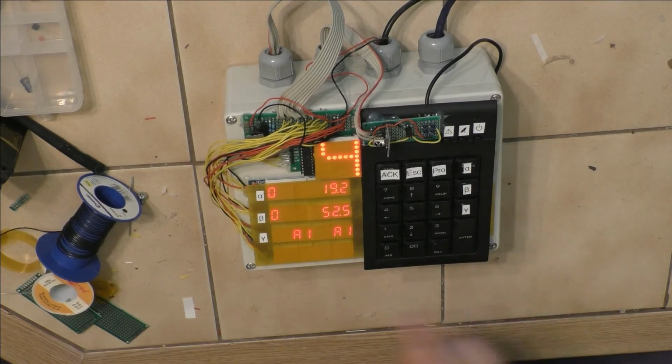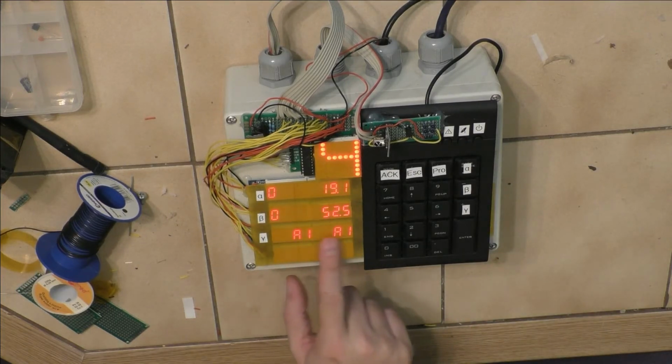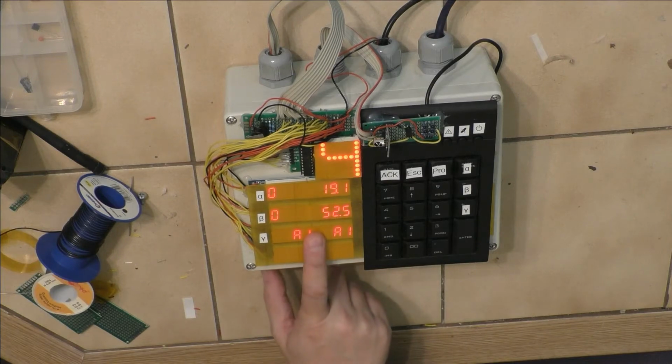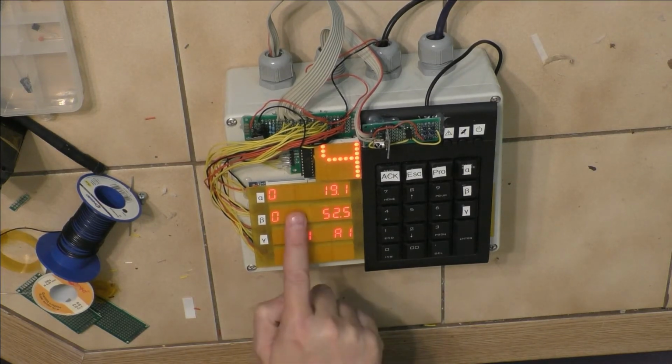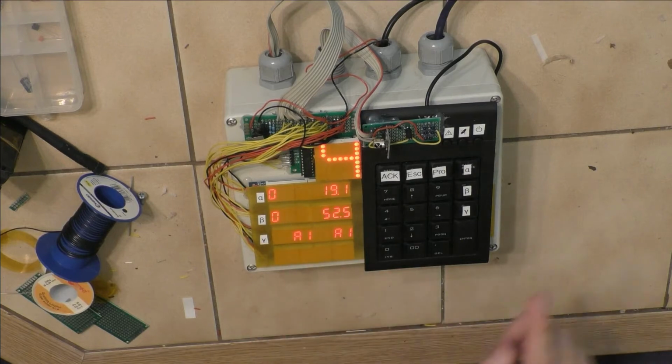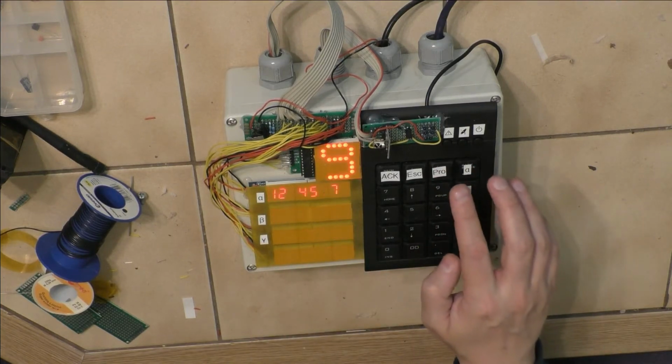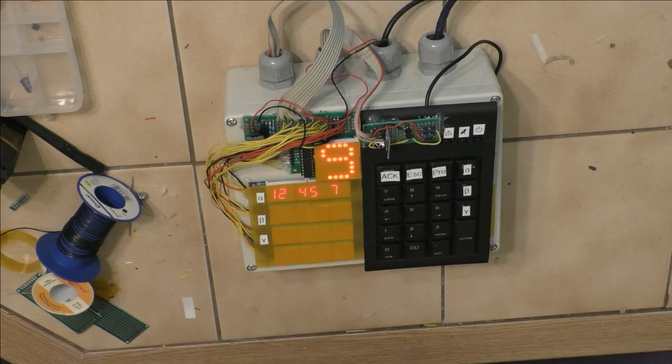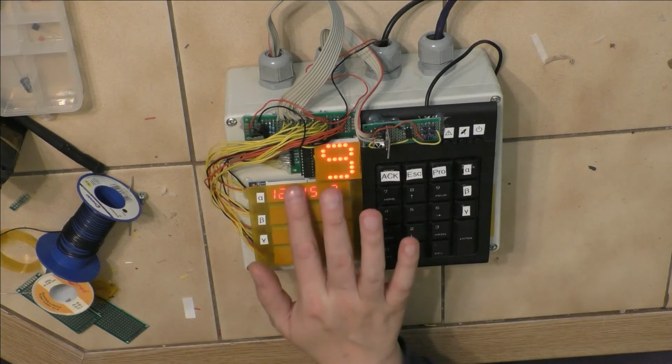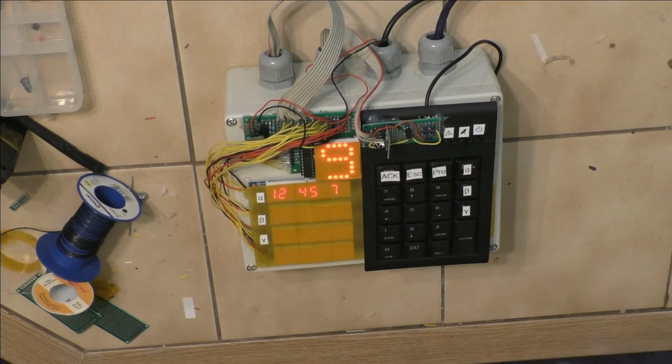We could actually say we want to turn off automation and turn on the humidifier manually. But if you turn on the humidifier before the switching off of the automation has been processed, it might switch the humidifier back off immediately.